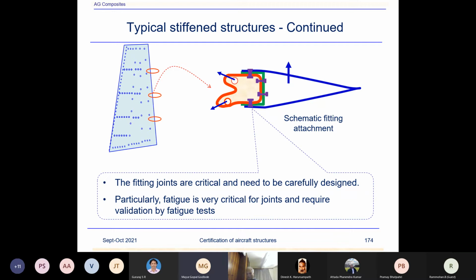Thank you, sir. Joints are more reliable than adhesive bonding. For adhesive joints, qualification becomes very difficult: the glue line thickness, its maintenance. There are lots of issues with that. It's not that it's not being done, but for the critical structure like the spar, currently I would try to avoid it. Fine, sir. Thank you. You're welcome. Good question.